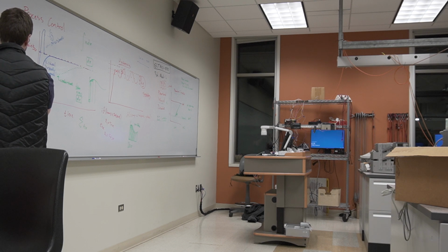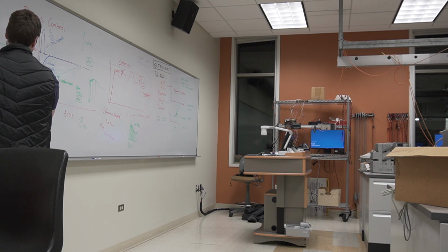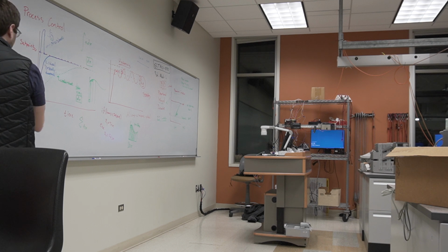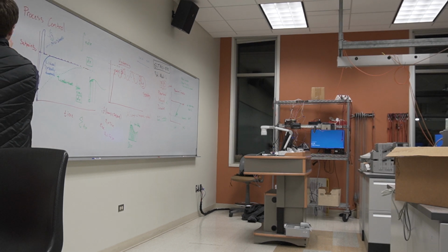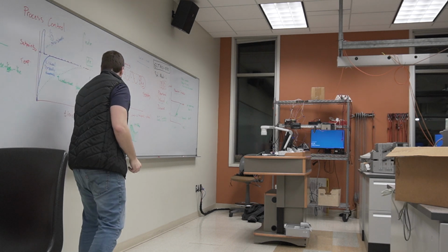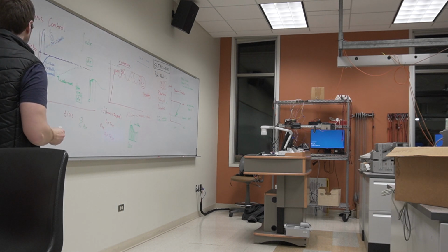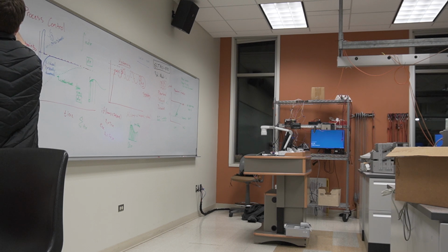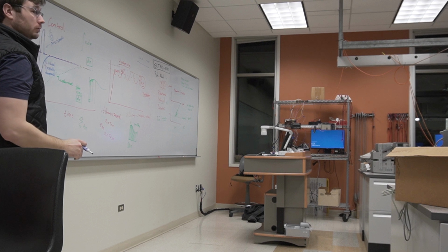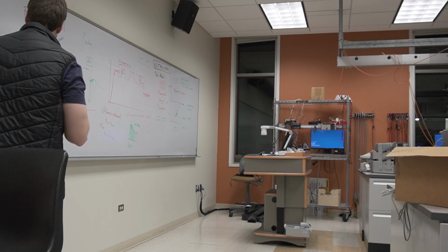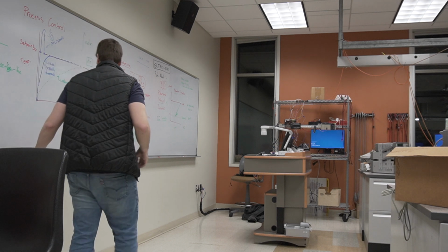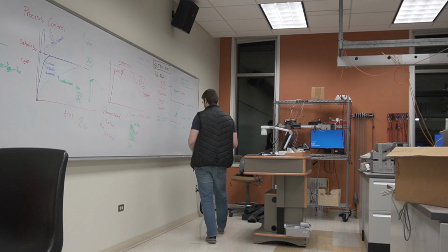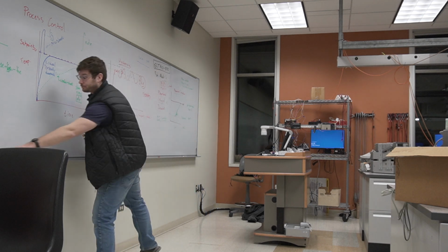Eventually, we're going to add really small E's, like half E and quarter E, and this doesn't build up quite as fast. And in fact, we might even overshoot. At some point, this I is going to grow so large that the P is telling us we need to be here, but P plus I says we're all the way over here. We swung around back this way. This is the downside of PI controllers, that they can oscillate.